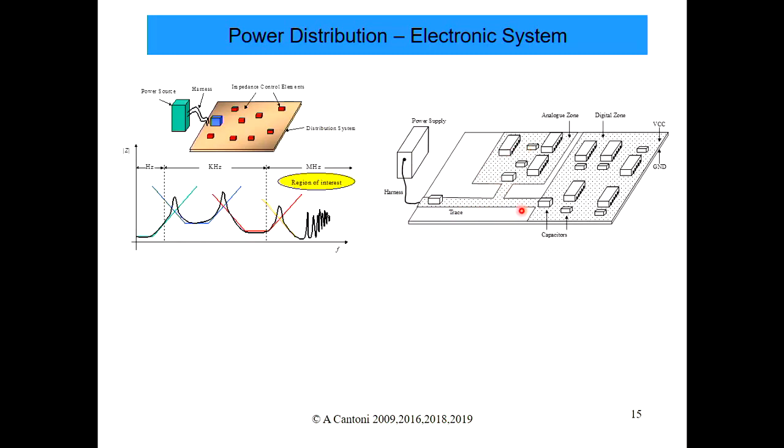these traces to the various components, and they're on different sections which might have these power planes, where underneath you've got the ground plane, and on top you've got this plane which carries the 5 volts or whatever it is, okay. And so at different frequencies, the response, if you're looking in at one of them, so this is a multi-port system, right? So you have perhaps the power supply, regulated power goes in at one port, and then at all these little ICs, you also have another little port that's tapping off the 5 volts with respect to ground, right? So you have a little ground pin and also the VCC pin, and also here where you've got these capacitors and all that to help smooth out all the power supply resonances, you also have ports, okay? So it's a multi-port system.